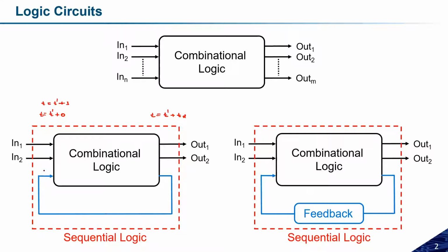Now the important thing, as I just told you, is the bistable one, which we need to discuss in more detail. So let us discuss the bistable circuit in more detail and see how it behaves. To understand the behavior of a bistable element, we need to provide the feedback properly so that we can have a feedback loop for the memory effect.